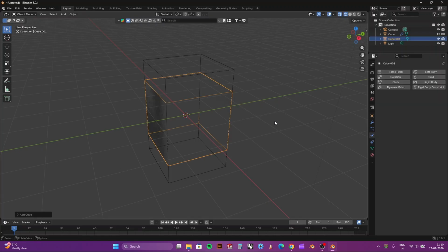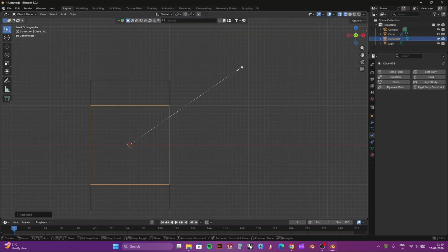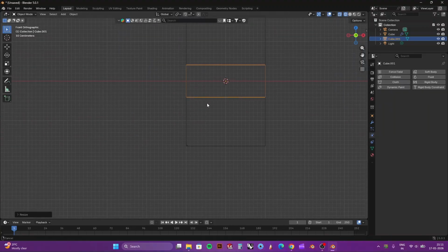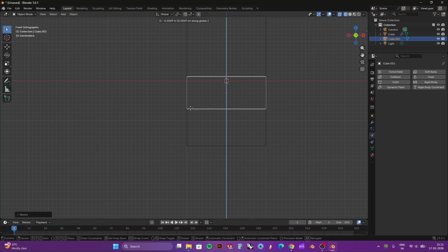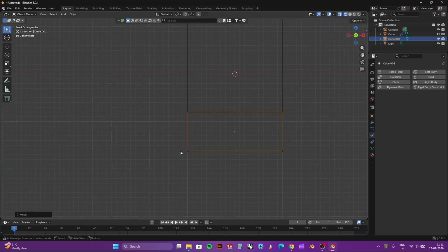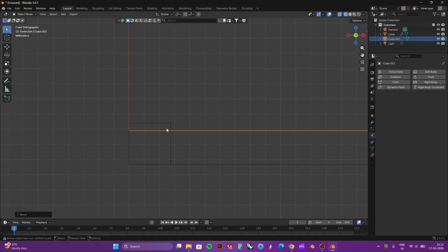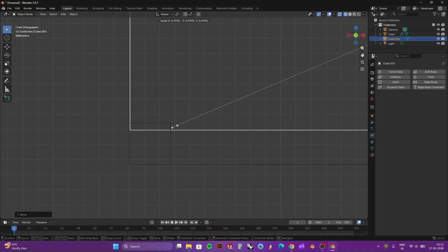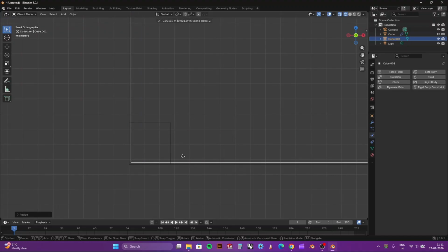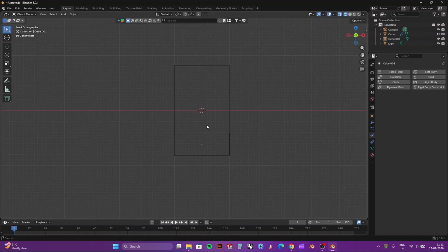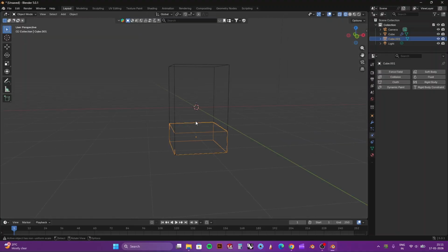We are now adding a cube. So this cube we will add as a geometry flow. Why? Because a water droplet will collide with it. So a water will collide with another water body and it will create a splash. So after adding this cube inside the main domain, just make sure that you resize it as it is smaller than the domain. Then only it will work as the fluid.